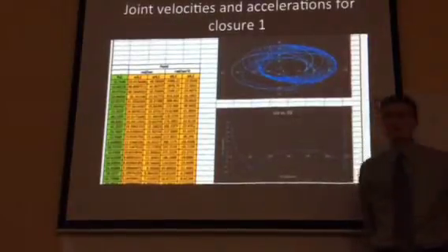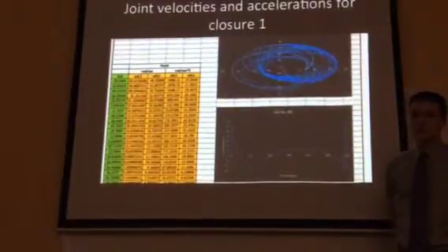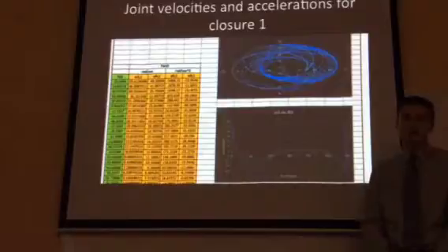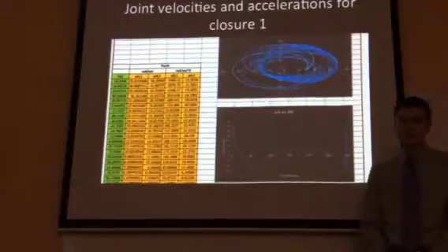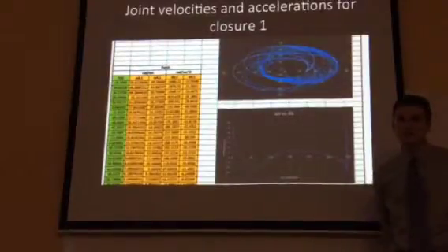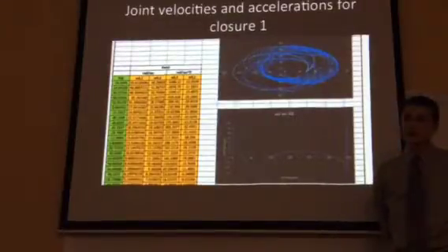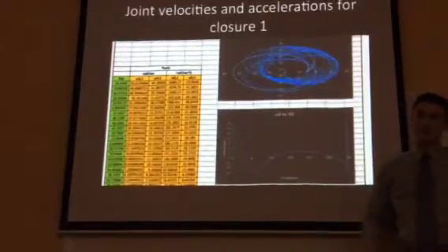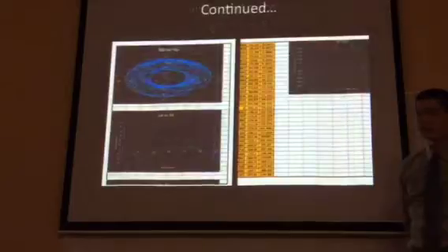When you're doing a quadratic equation, you get two answers. So this is the first set of answers. And then when you're calculating the relative velocities of the links, usually matrix form is the easiest when you're just trying to figure out one or two unknowns. But because I'm trying to do it for 360 different degree points, I just put in a very complicated equation, went all the way through for the first cell, and then copied it all the way down. Right at about 350 degrees, it's where it's changing, a very unstable point for the mechanism.